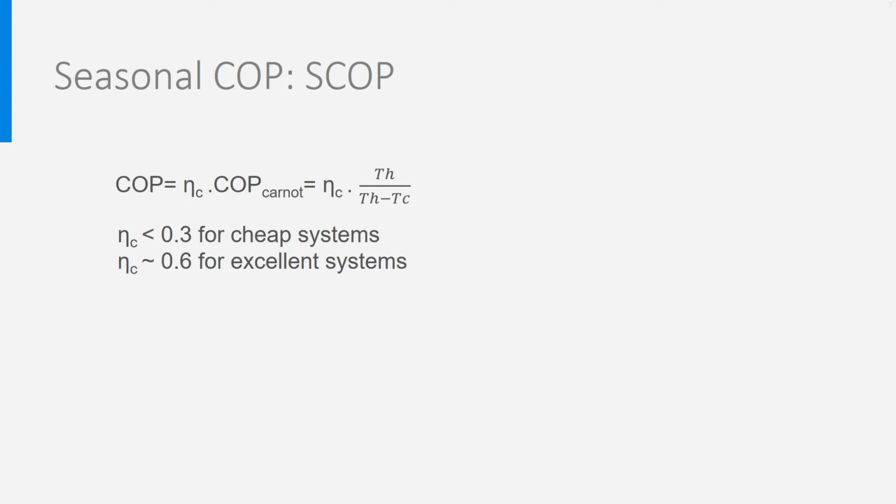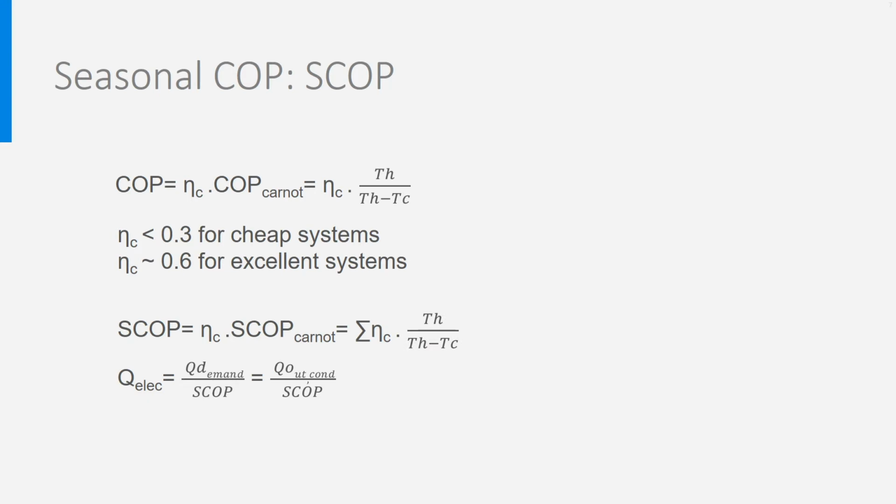In general, the COP varies also with the load, and we know from the course Energy Demand in Buildings that the heating equipment will almost never be needed at full load because the energy demand varies a lot all over the year. This is why producers of heat pumps must specify the COP for different outdoor and load conditions and provide a formula to calculate the seasonal COP depending on the frequency of occurrence of partial load for a certain climate.